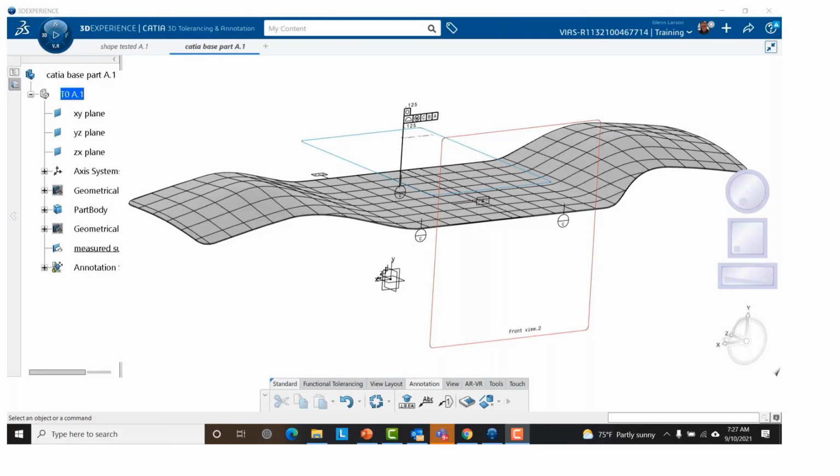That's a really good question. It's always best, if you're using a CMM machine or a scanner, to set the datum up first so that it comes in the same position. Glenn, this is Danny Alcini. I can also comment on that as well. You can use registration points, which allows the software to key off of the geometry.